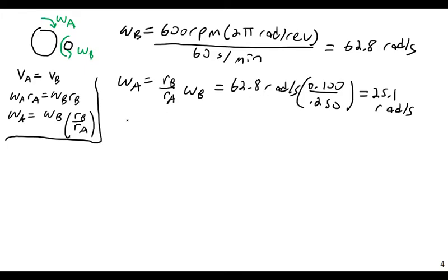Next, I want to find the moment of inertia of each of these things. So I bar A, or IA, let me leave the bar off. I think it's obvious that we're talking about the centroid, which is the center of rotation in this system. IA is equal to MA times KA squared.